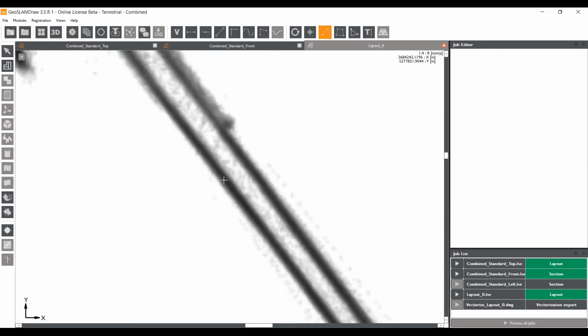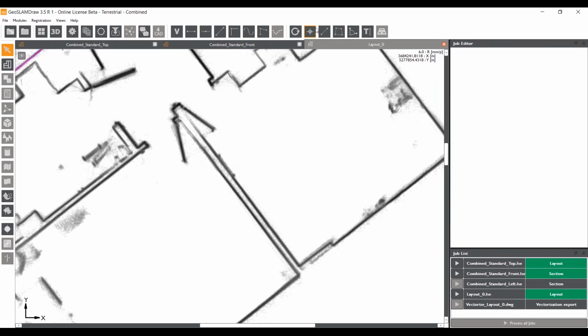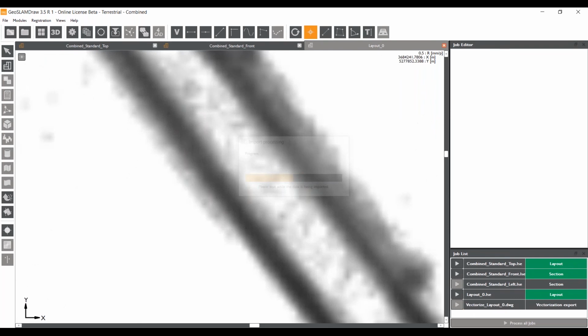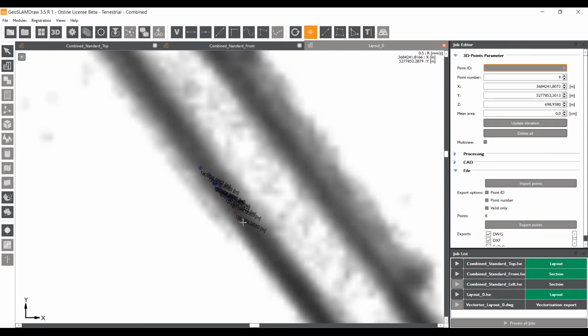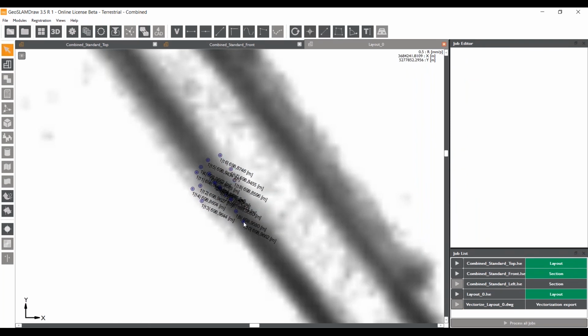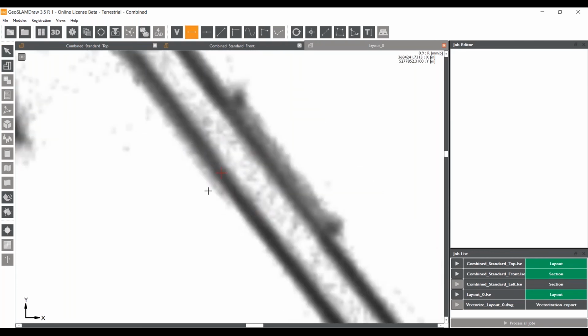Normally noise in point cloud data looks like this: you have points which are distributed, the most points are normally distributed directly on the wall, but you have some outliers, which are the noise, which go out there into and outside of the wall. But since we have the most points on the wall directly, we shade the pixels there a lot darker, and then you're able to see that there we should draw the line directly. And with that, you can see that the snapping function is going into the middle of the line you see here.